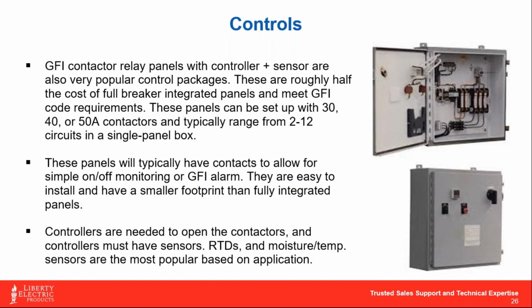When we talk about contactor relay panels, we touched on it just a second ago. These are very affordable, usually a standard bearer on a lot of systems because they're pretty low cost, but your labor units go up, okay? You've got to bring over each circuit to the contactor relay panel. Now, the contactor relays can also take care of your GFI code requirement. They will need a signal to close the contactor on them. So generally with a contactor relay panel, you are going to have a controller and a temperature sensor with that, depending on who the manufacturer is.